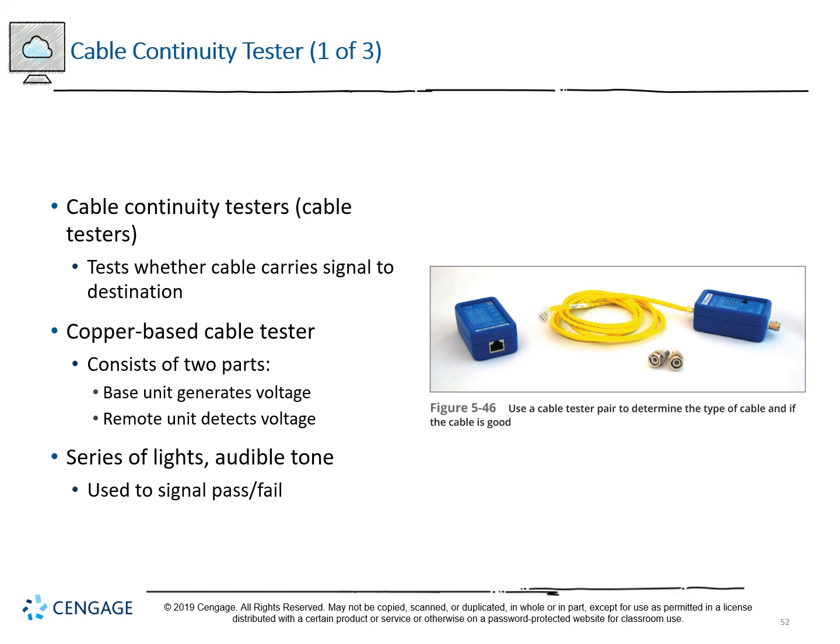Continuity testers are essentially doing something that the multimeter does, which is checking to see connectivity, but it's a little bit more intense in that it checks for whether or not the signal is being carried completely or not. So this will be making sure that the pairs are all lined up correctly and able to transmit.